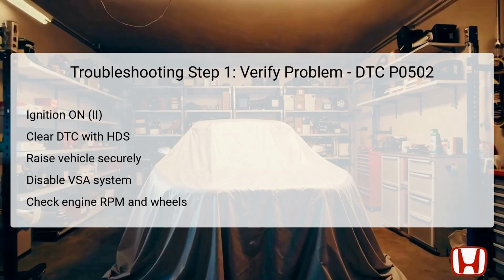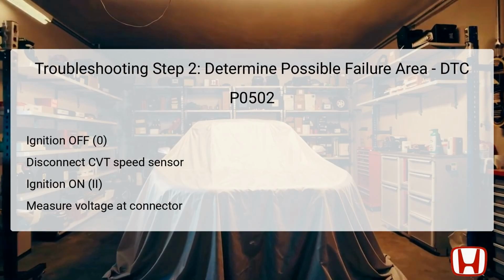If the wheels slow down and stop, proceed to check for any pending or confirmed DTCs with the HDS. Is DTC P0502 indicated?